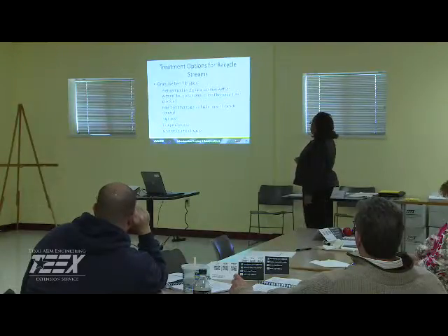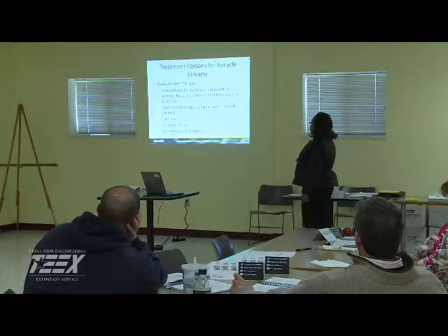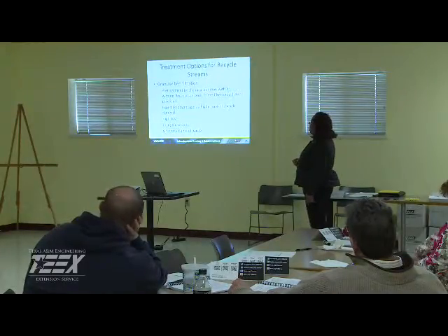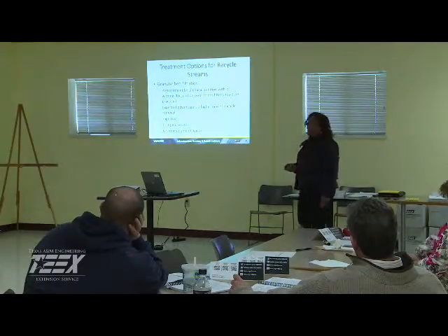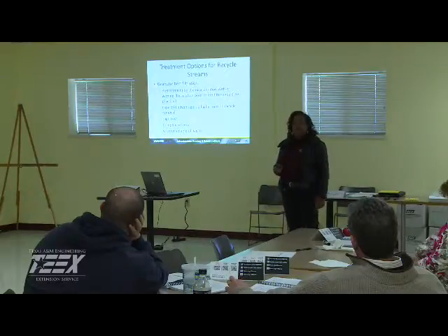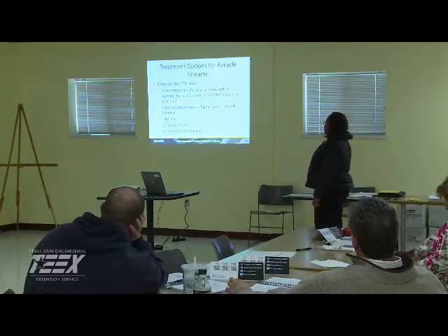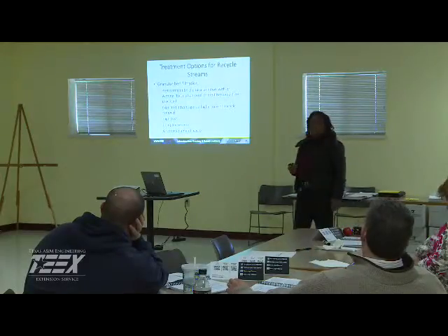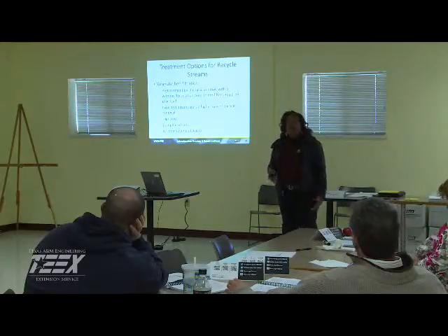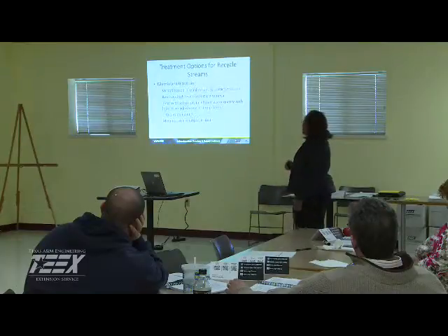We also have granular bed filtration options. Here again, pretreatment by chemical addition with or without flocculation prior to the filter. It's usually practiced with beds. The expected advantage is a higher rate of particle removal, but it's going to cost you a little more. The process can be complex, and you create a greater volume of waste. Now you have to figure out what you're going to do with that additional waste.